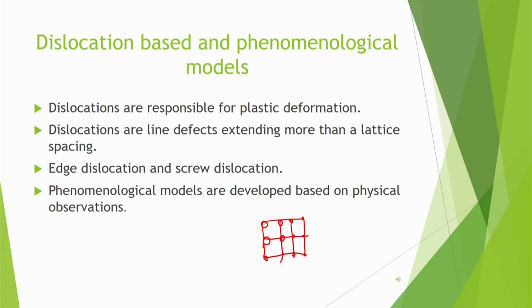There will be a lot of defects. Some defects can be point defects, that means there will be a void in the material. In some cases some other atom may enter inside and occupy that site, that means it may substitute the material. So, a substitutional defect is there, that means inclusion of some foreign material, or the main material atom may be removed from there.